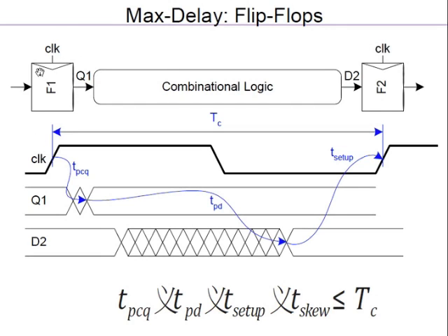At the rising edge of the clock, the data is transferred to the input of this pipe stage. The data flows through, and by the end of the clock period, the data is ready to be captured by the set of flops F2, which then feeds it to the next pipe stage. This is basically how pipelining works.